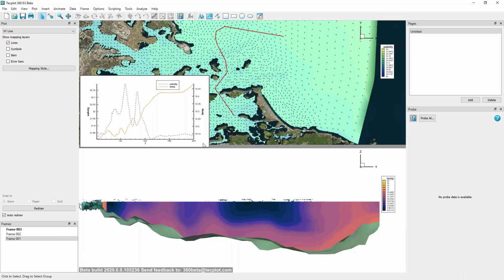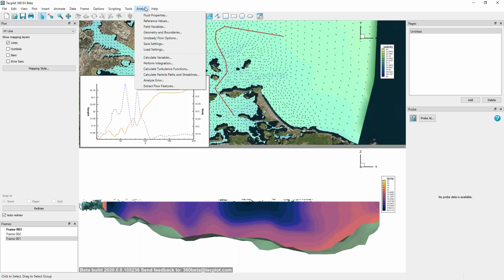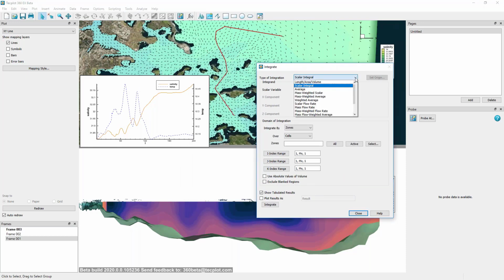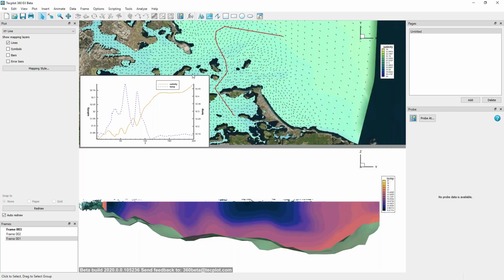In this case, the I variable that I selected, like you saw, is just the points along the polyline. You should be able to, from the integration tool, calculate the length along the polyline and then create a variable from that. I don't know, Scott, do you have any other ideas for either bringing in a distance variable or calculating a new distance variable to use as the x-axis?